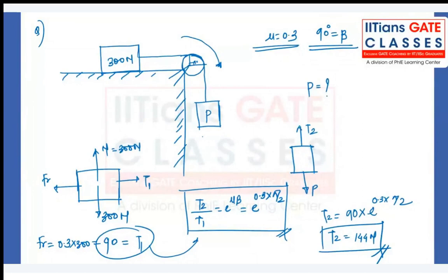But even if it is not, is there any other force? Do you agree this P is trying to pull this even if you don't apply the force? So if it is applying that force, that will be the tension side because this entire system is trying to move towards the right-hand side, and that is why this is a high tension side. Always try to draw the arrow in the direction of motion, and the arrow indicates the high tension side.